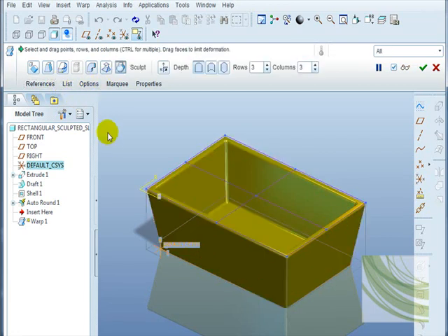Click the sculpt option. Notice it's produced a grid on the shape, in this case just a 2x2, optional 4 individual spaces. I want to work on the ends, so I switch the orientation of the meshes until I get the end. I want that to be applied symmetrically to the opposite end. So click on that icon, just selecting one node or intersection of the mesh. I can shape those ends.